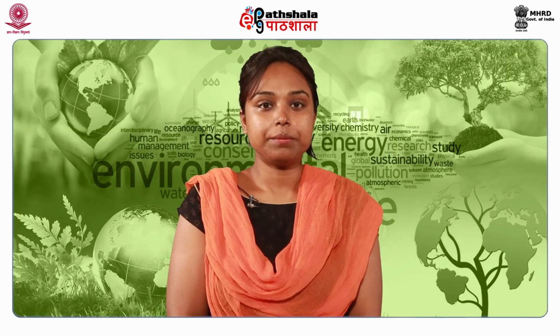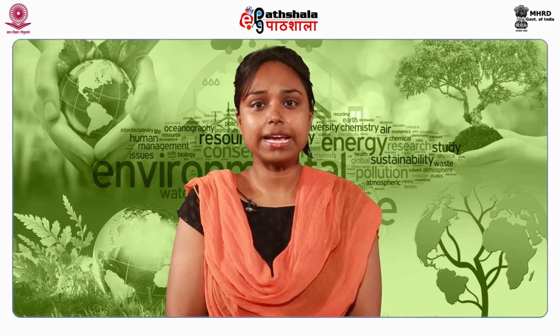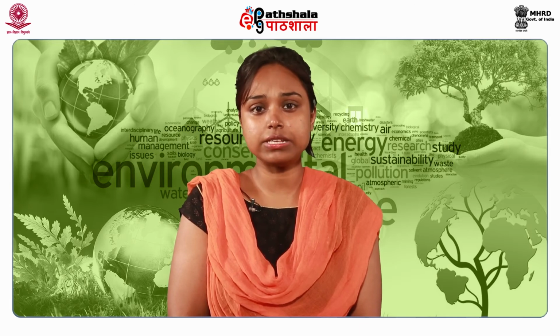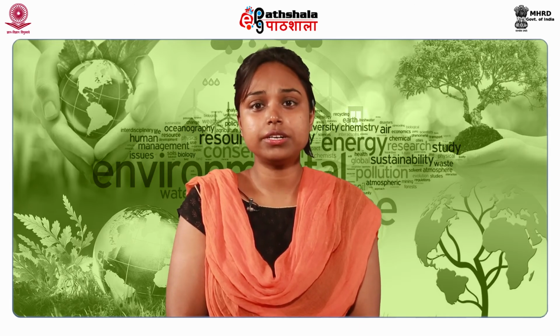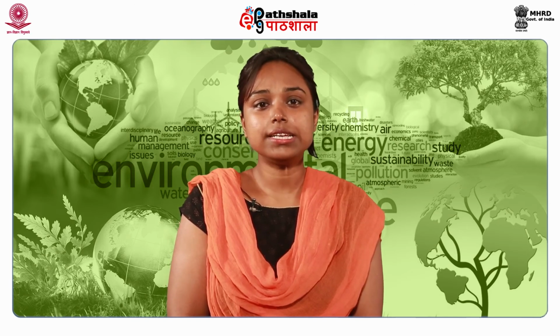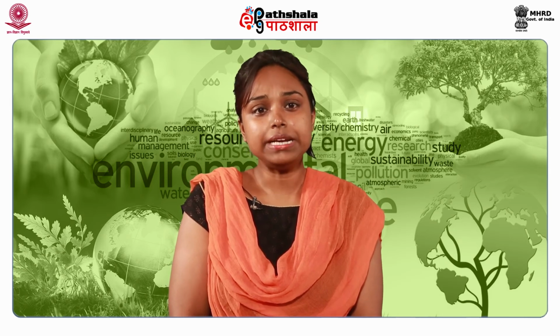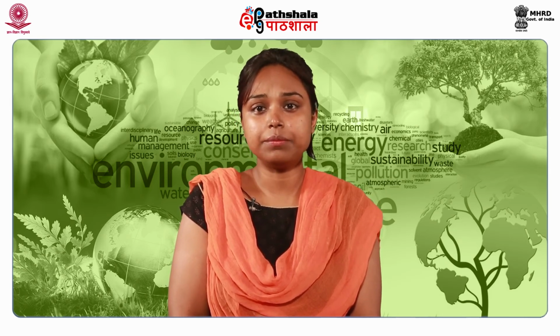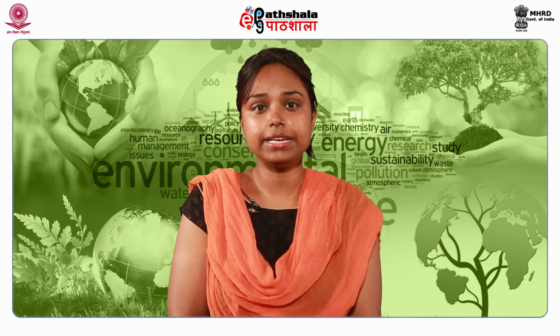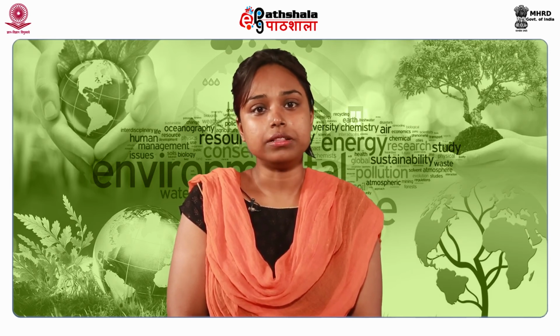Now, chemical tests. A chemical test such as a leaching test is generally performed as an endorsed toxicity characteristic leaching procedure, TCLP, for the identification of chemical constituents in the stabilized waste. The stabilized waste should meet the best demonstrated available technology, BDAT, standards before disposal to the secure landfill.